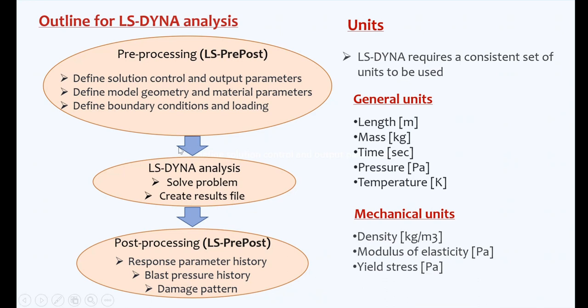Before that, I'll just provide you an outline of the LS-DYNA analysis that I have already explained in the previous slides. First is pre-processing. For pre-processing and post-processing, we will be using the LS-PrePost software, which comes with LS-DYNA, and it is free. I think you all have already downloaded it and started using the software. In pre-processing, we define the solution control, output parameters, model geometry, material parameters, and then boundary conditions and loading.